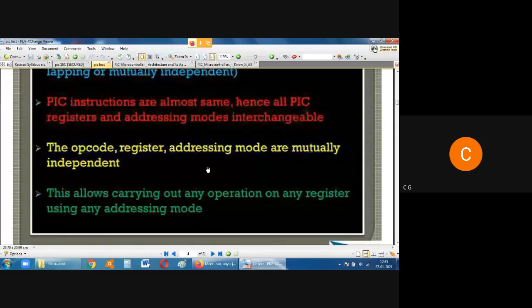The address is a 4 digit hexadecimal number, like 0000 or C100. That is broken into two parts, C1 and 00. So first you write the LSB, then you write the MSB. So the instruction, data and address of the memory location are coded with the same wording, 00 to FF.